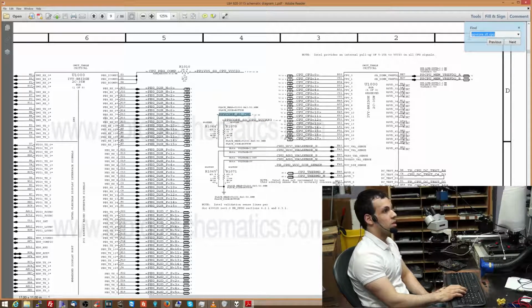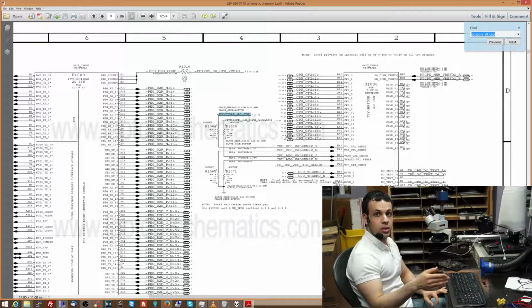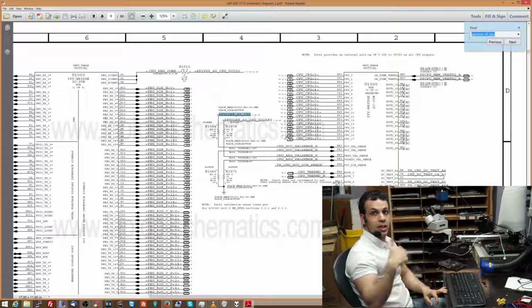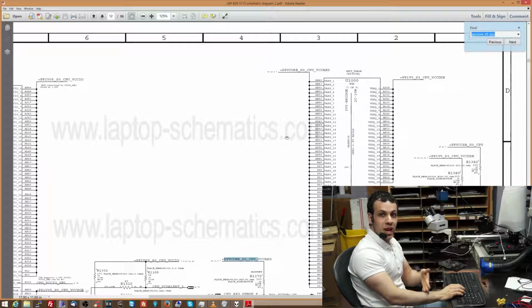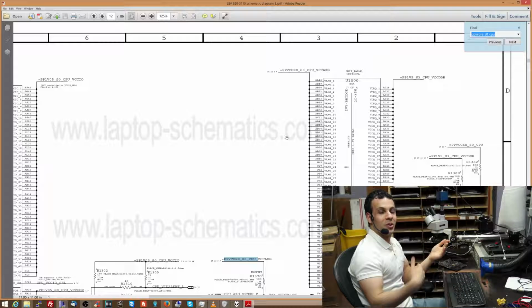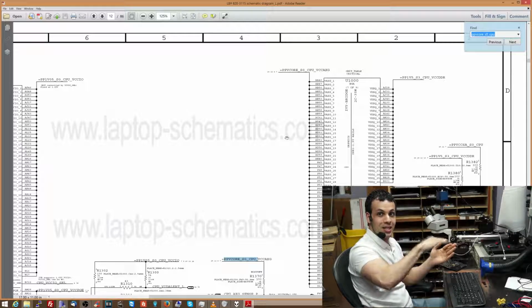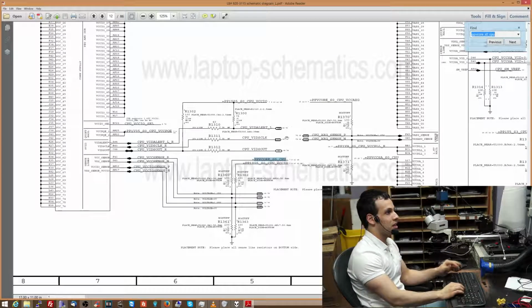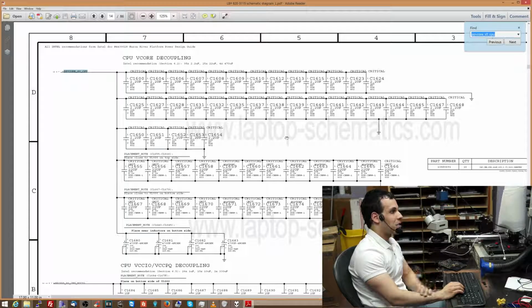And the way that works is that you're going to take a bunch of pulses and turn those pulses of 12 volts into a smooth 1 volt. So even though those pulses of 12 volts average out to 1 volt, the CPU doesn't want to see 12 volts now and 0 volts, 12 volts now and 0 volts later. The CPU wants to see a constant 1 volt, or else it's not going to actually do anything and your computer's not going to work. So I showed you how the inductor and the capacitor even it out.